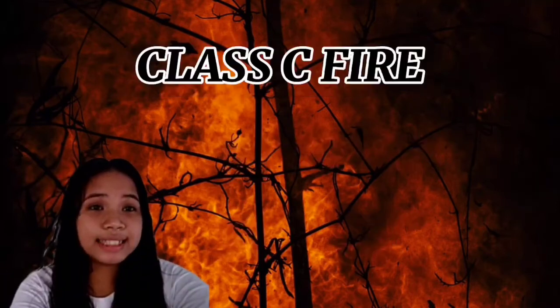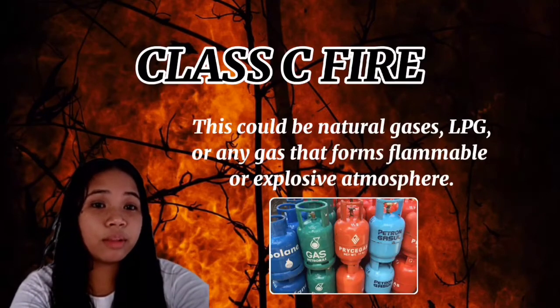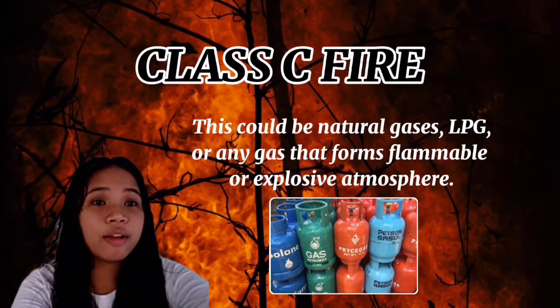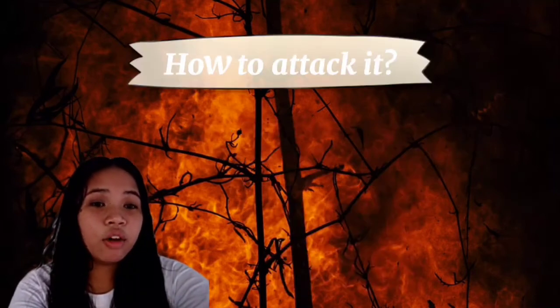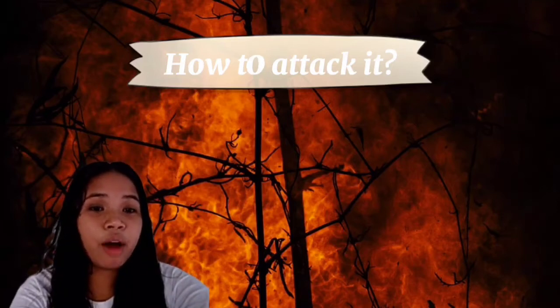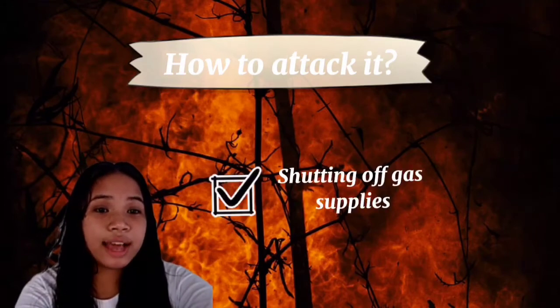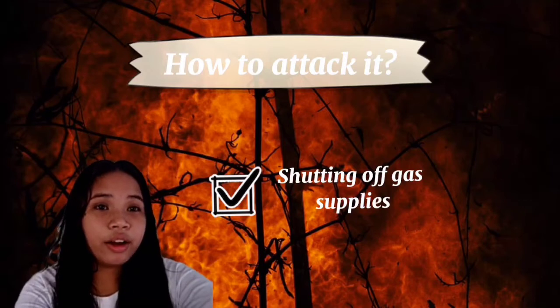Third would be Class C, involving gases. This could be natural gas or LPG or any gases that form a flammable or explosive atmosphere. The only type of extinguisher that attacks this type of fire would be the powder extinguisher. Keep in mind that shutting off the gas supply should be the first thing you do in this type of fire.